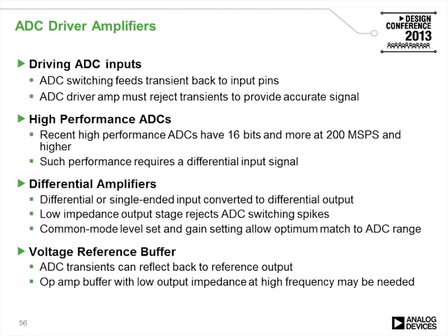ADC driver amplifiers have been designed to drive ADC inputs. ADC inputs usually present switching transients. An amplifier must settle after such transients and deliver high resolution and high performance. High performance ADCs also require differential input signals. This may be a problem for circuits that deal with single-ended signals because those need to be converted to differential.